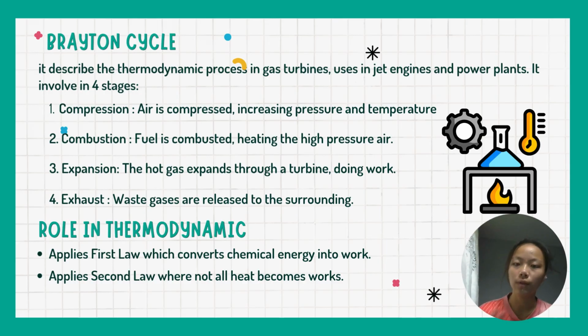So we go to the first stage, which is the compression. The air is compressed, which will increase the pressure and the temperature. The second stage, combustion, where the fuel is combusted, which will heat the high pressure air. The third stage, expansion, the hot gas expands through a turbine and it will do work. The last stage, exhaust, the waste gases are released to the surroundings.